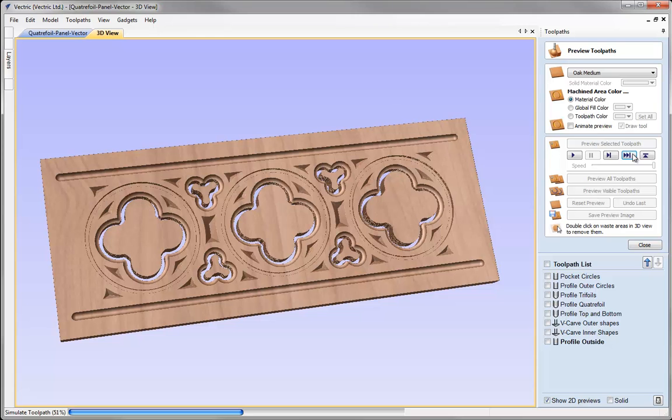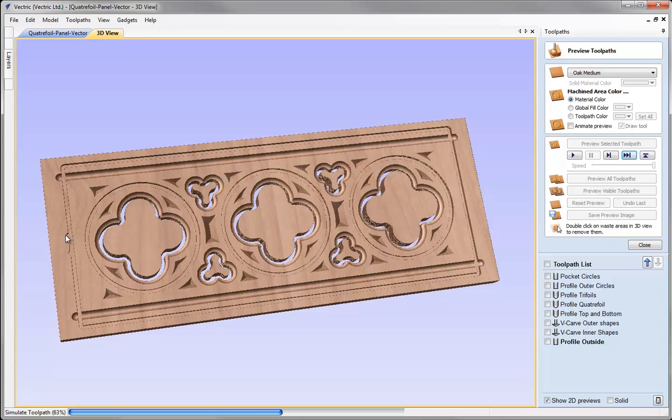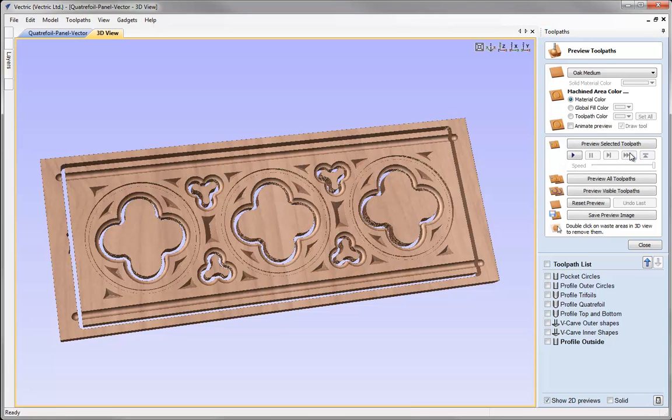And that's all the shapes now, so it should now start on the actual cutout of the outer vector as well. So let's step through. As you can see, that's done that. You can also see that the lead in and lead out is visible there. And there we go. As you can see, that's cut out exactly how we expected it to.